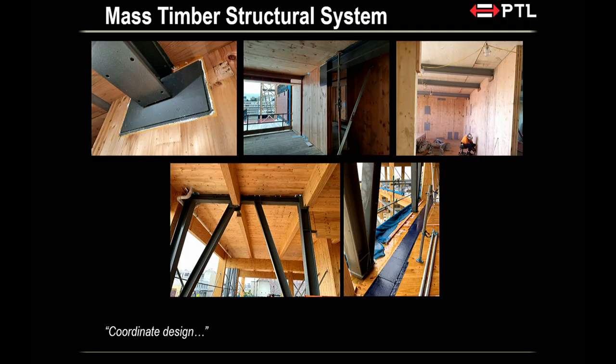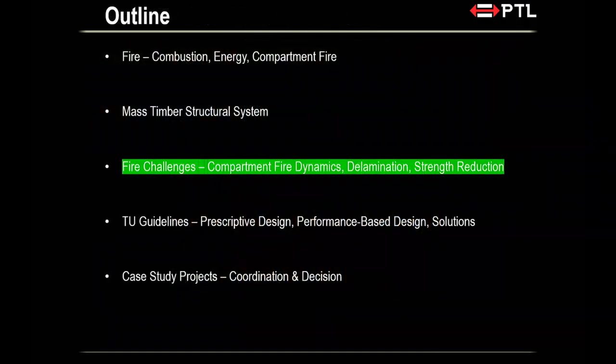In this case, here you have an EBF: basically, a steel column going through your CLT floor, the floor sits on top of a beam, and you have a brace coming in at an angle, that sort of thing. So what I wanted to say here is, it's very complex stuff, so we need to coordinate. There needs to be a dialogue between the structural engineer, fire engineer, and also the architect, to achieve a building design objective.